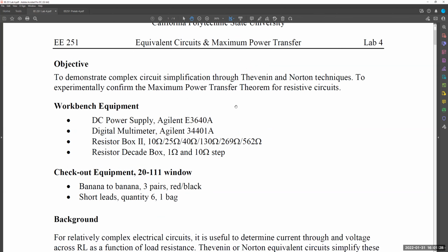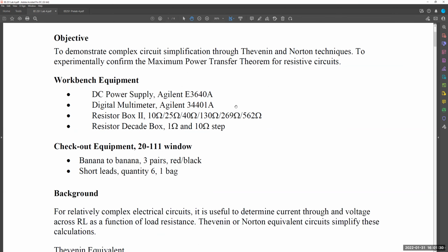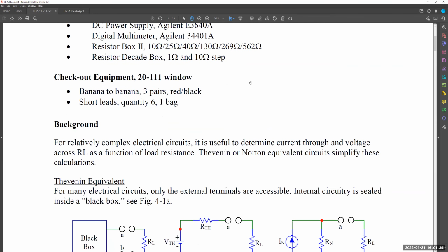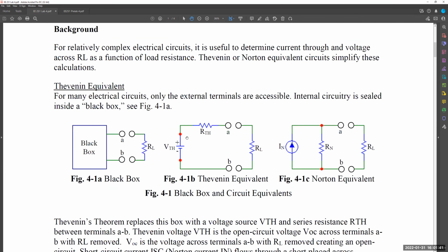There was a French telegraph engineer by the name of Leon Charles Thevenin, who postulated a theory that you could represent a large linear circuit comprising linear elements with just a single voltage source and a single resistor in series. That voltage source is known as the Thevenin voltage. The resistance is known as the Thevenin resistance. And that circuit is known as the Thevenin equivalent circuit.